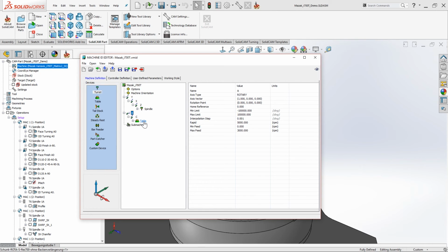In most cases this will be a good definition, but some machine brands have this vector of rotation on the rotary axis switched in the different direction. So I'll go to the A-axis, and this axis is rotating around the X in the negative, and our C-axis over here is rotary, and it's also rotating around the Z in the negative.